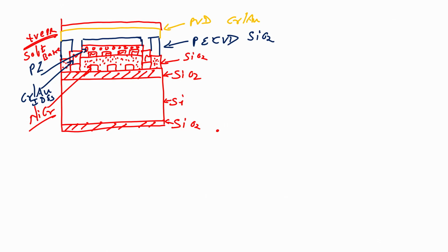After spin coating my positive photoresist, I will go for soft bake, and when I go for soft bake, I will then follow with loading the mask, and my mask is such that it will protect, because it is a positive photoresist, I want to have a bright field mask which will protect the region in the way I am showing you right now.